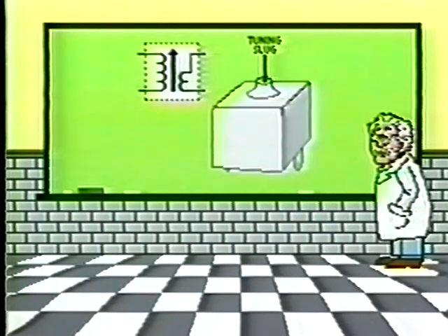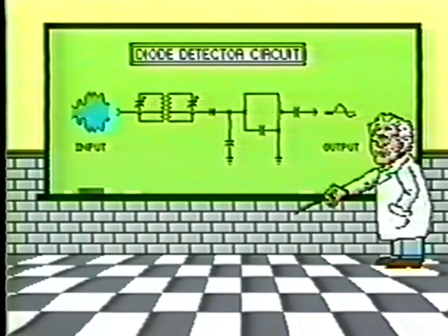The IF transformers used to couple the signal between the IF stages are generally encased in an aluminum can to reduce the possibility of stray electromagnetic lines of force affecting other parts of the circuit. The primary function of the AM detector circuit is to separate or demodulate the audio information from the carrier signal. The AM signal is demodulated in 3 simple steps.